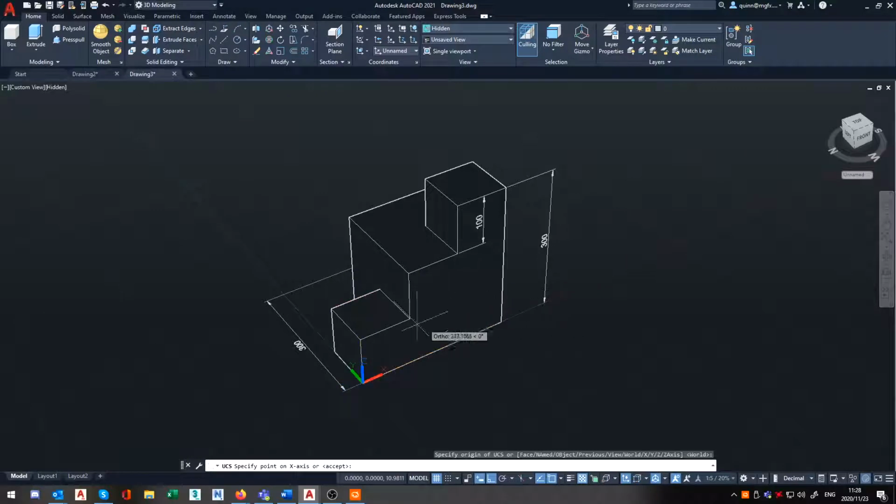The base thing you can do here is, once you've placed it, before you click, read in your command bar what it's asking you, and this will help you figure out what you're trying to accomplish. For instance, let me click that again. It says specify base point. Specify where the x-axis is running. So in this case, maybe the x-axis is running in that direction. Specify the XY plane, so basically it's asking you to specify the Y. When you specify the Y, you'll notice that our grid actually flips.